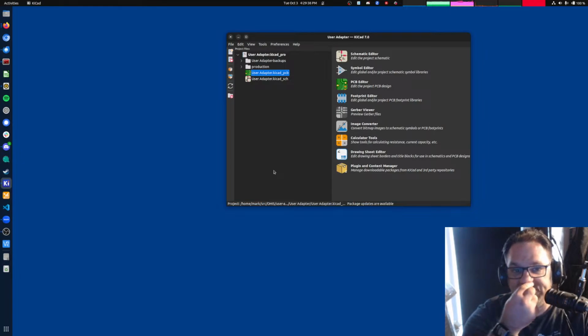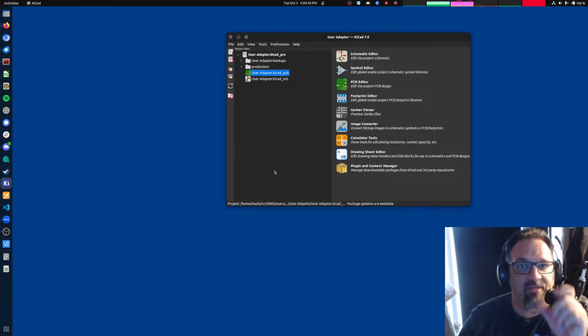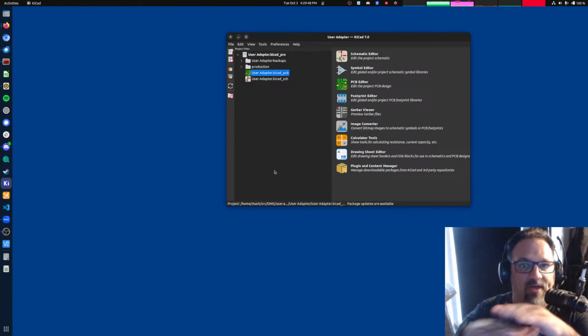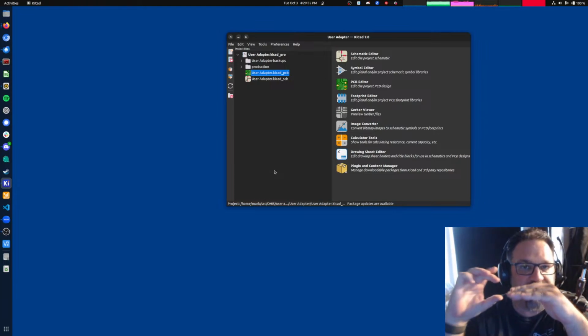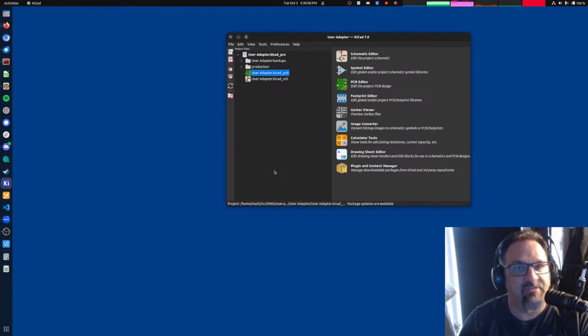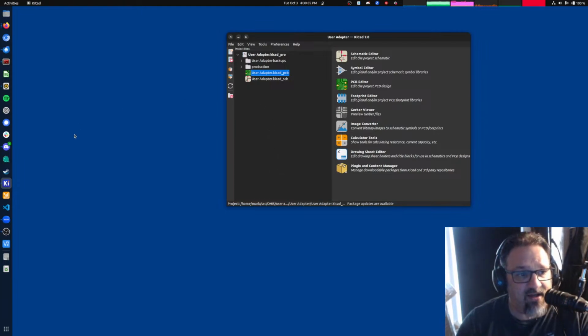I may do one more live stream where I lay out the top board. Layout is a strong term. Got to go figure out where the PTT button is going to stick through, and whether the separation of those two boards means I'm going to need to do a cutout notch for the RJ45, or whether the board's going to go on top of the RJ45 where the board is just solid all the way through. So I got to go figure that out. Then I will be ordering boards and turning this into a kit and posting all of this.